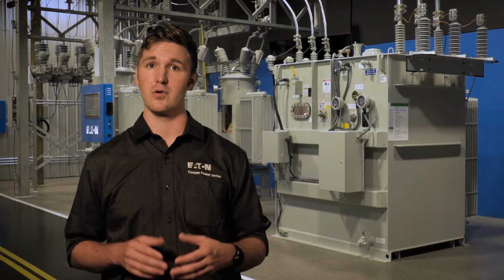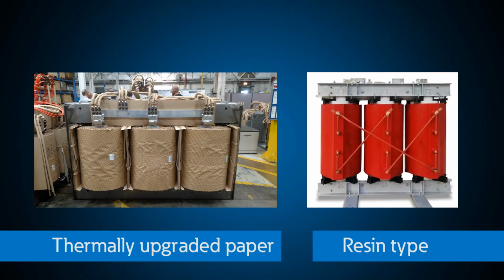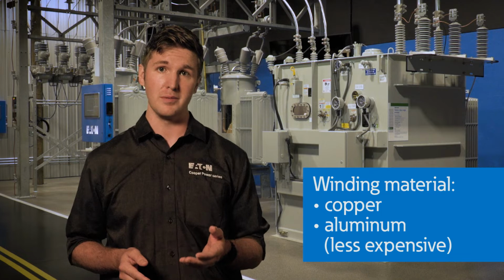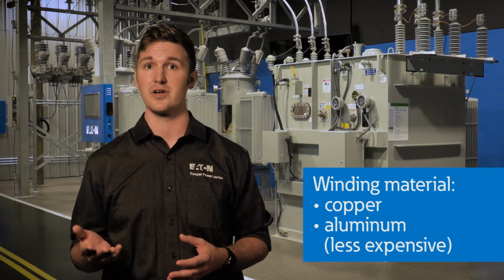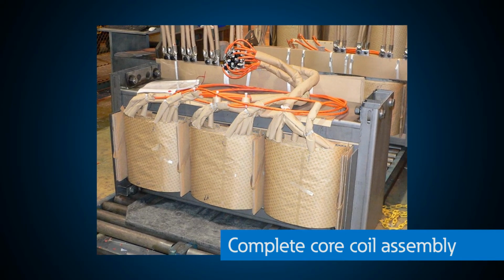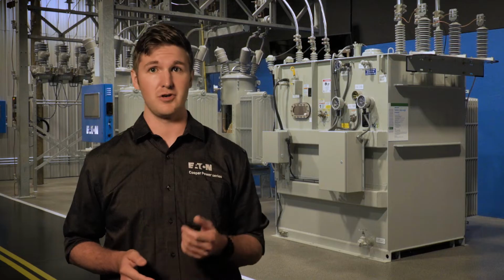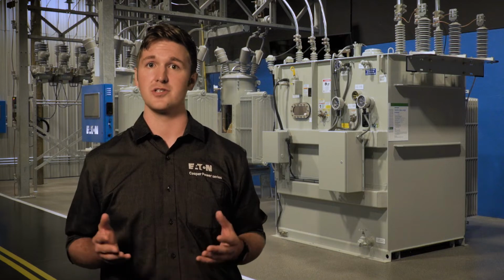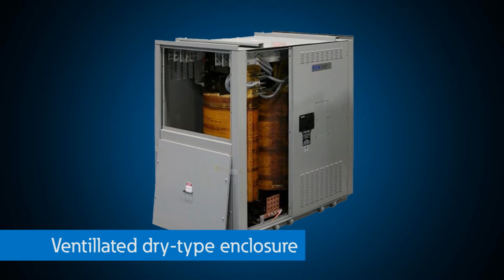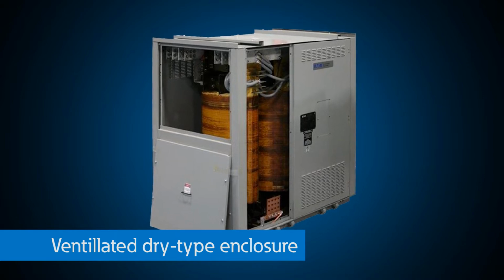Thermally upgraded paper, or in some cases resin, acts as both a mechanical and dielectric barrier for the raw conductor of the windings. The winding material can be copper or aluminum, with aluminum typically being less expensive and offering similar performance on an optimized design. Once the windings are on the core, the coil assembly is complete. For dry-type transformers, the construction is nearly finished. The core coil assembly must be installed in a ventilated enclosure and the appropriate terminations added.